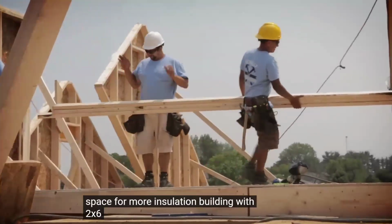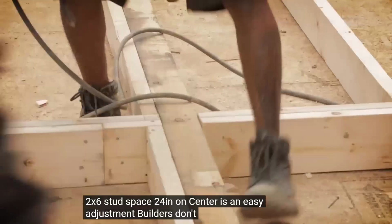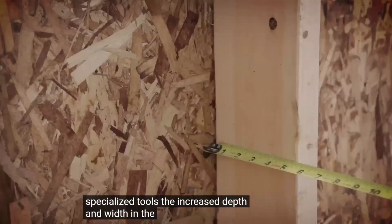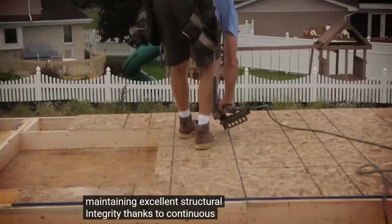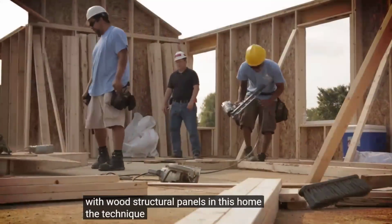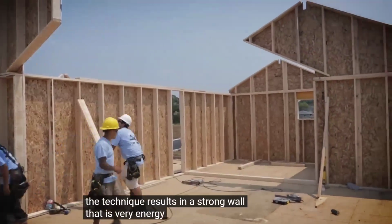Building with 2x6 studs spaced 24-inch on center is an easy adjustment. Builders don't need new or specialized tools. The increased depth and width in the wall cavities leaves much more room for insulation while maintaining excellent structural integrity, thanks to continuous sheathing with wood structural panels. In this home, the technique results in a strong wall that is very energy efficient.